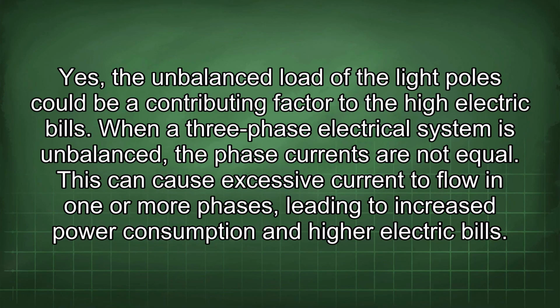Yes, the unbalanced load of the light poles could be a contributing factor to the high electric bills. When a three-phase electrical system is unbalanced, the phase currents are not equal. This can cause excessive current to flow in one or more phases, leading to increased power consumption and higher electric